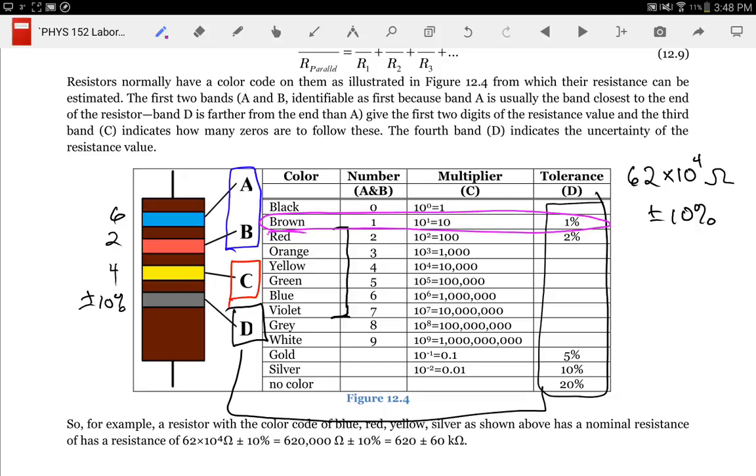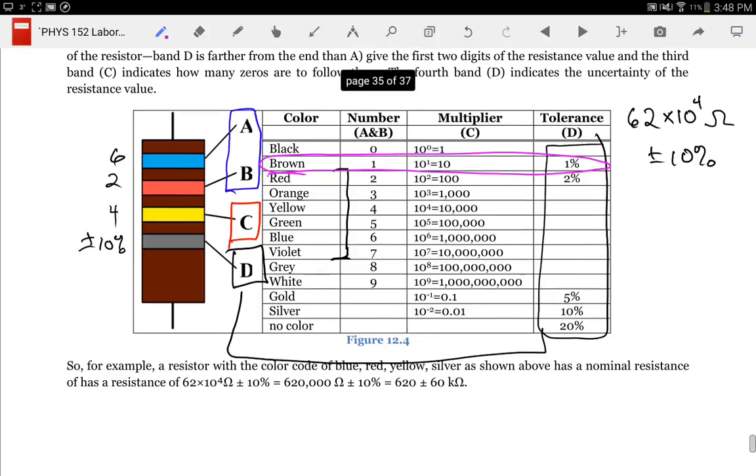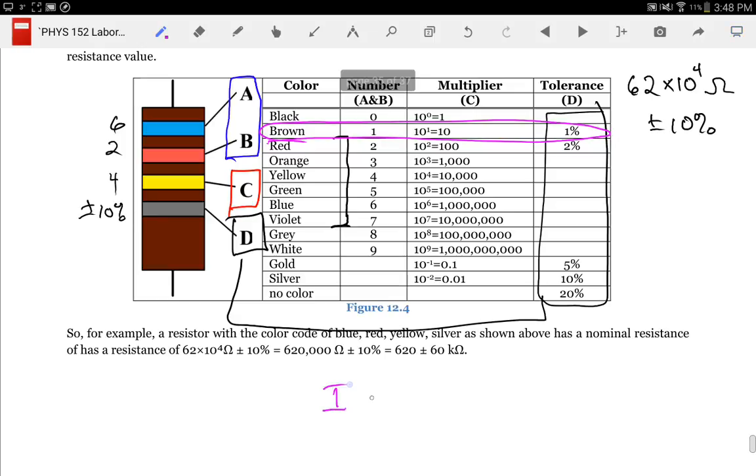The reason we're doing that is because we want to make sure the current is less than our maximum. I is V over R. The maximum voltage we're going to use is 10 volts, and the minimum resistance we would have would be 100 ohms. That would be 0.1 amps. That's why we're setting that limit.